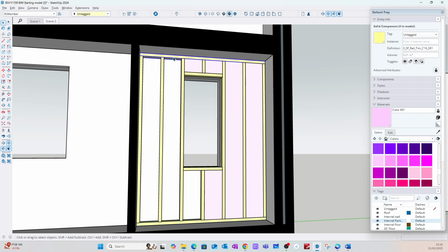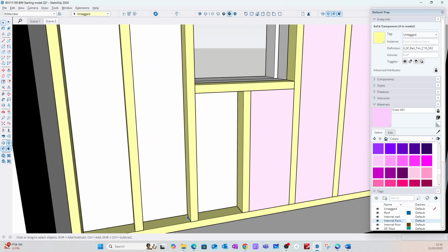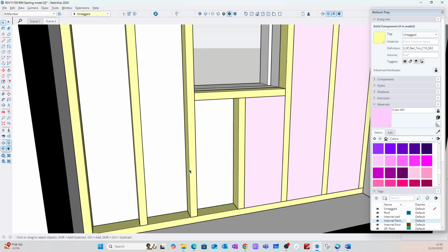That top rail would also be just called a rail, number one. And then this lintel and the sill, well, they're just rails number two, made out of C16. I've happened to make that 95mm by 45mm, but you could make that slightly thinner. You couldn't make it any thinner than 38mm, but for just now, 45 is fine.